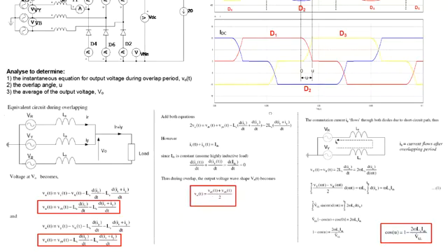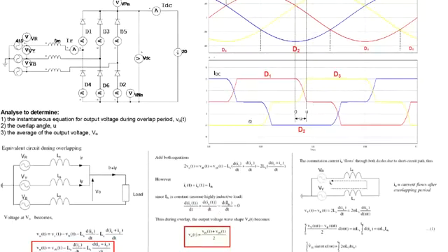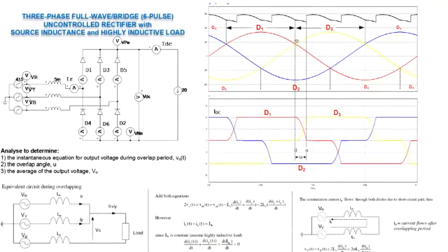This is actually the average. The voltage here, V out, is actually the average between the two line-to-line voltages. There's a line-to-line voltage across that and across that. And if we look closely, the V out during this overlapping period is actually in the middle between the two line-to-line voltages.